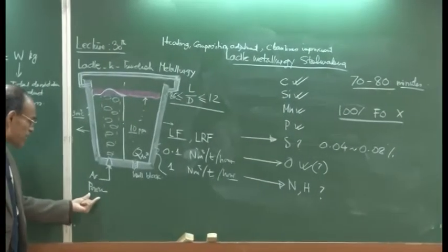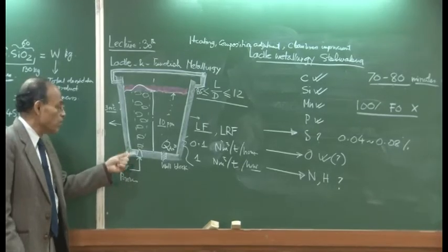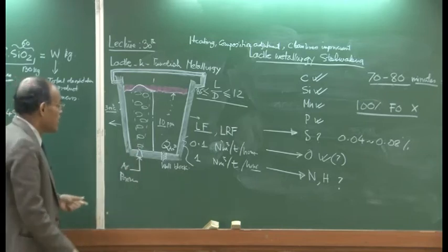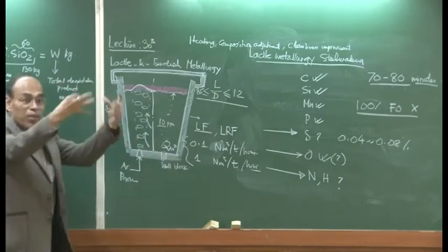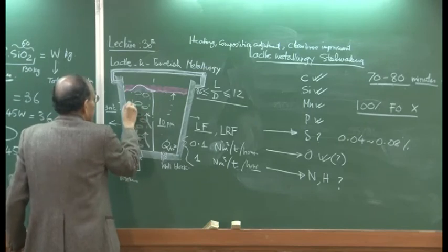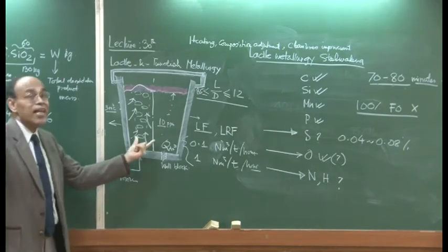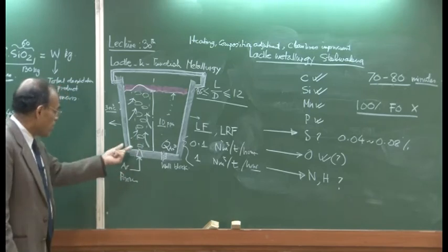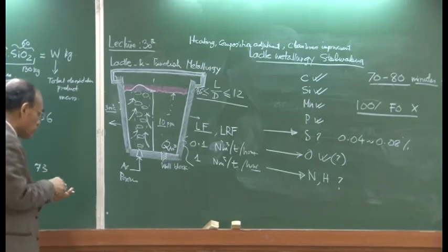Now, the gas which you inject here rises up because the gas is lighter, because of its potential energy. As the gas goes up, it entrains surrounding liquid along with it, and as a result you generate a toroidal current within the system. So, it is basically a buoyancy driven system. The buoyancy force applied by the bubbles on the liquid actually manifests in the stirring of the bulk